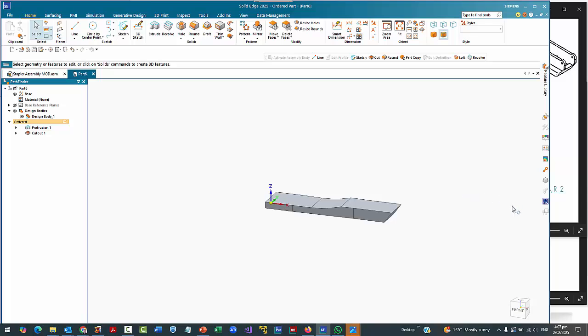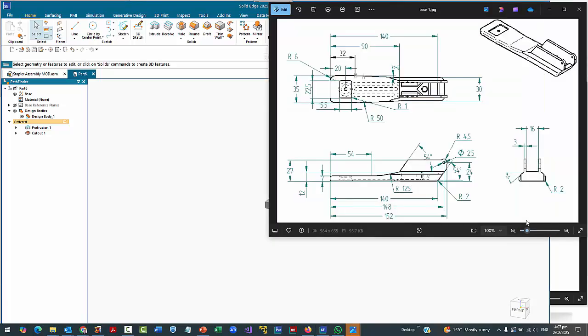So the next thing I will add is one of these fins here. So this comes from that intersection point where the arc runs out, 54 degrees up. It's coming up to a total of 27mm high, so 15 up from where it was. We've got a 4.5mm rad on the end here, and the intersection point of that is 148 and 24 up.